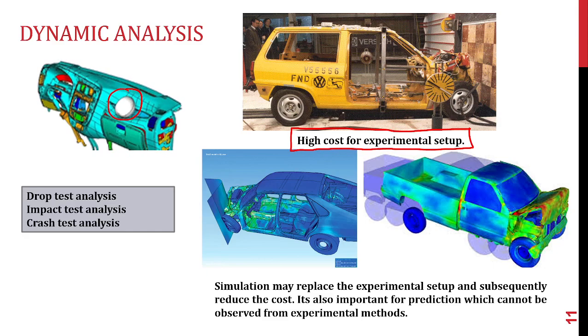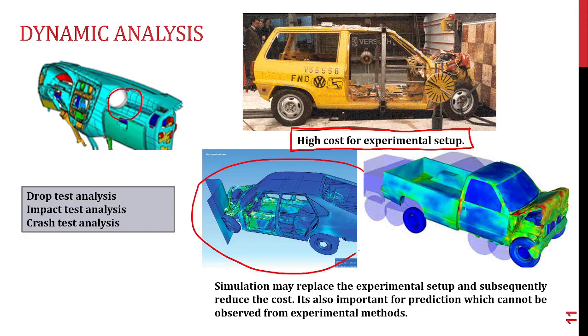And if the real car crash experiment matches your FEA, it is very, very good for the next iteration. Because with crash tests you can iterate. If there is any problem with the front bonnet, you change the thickness, change the material, elasticity, tensile strength, many things.